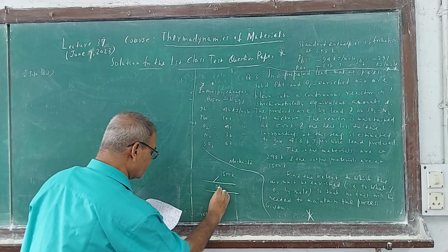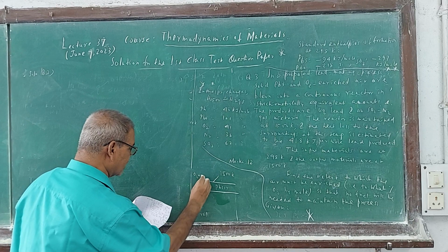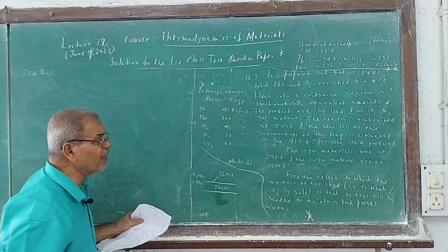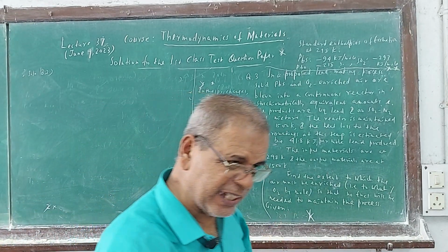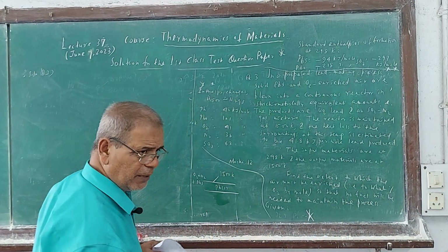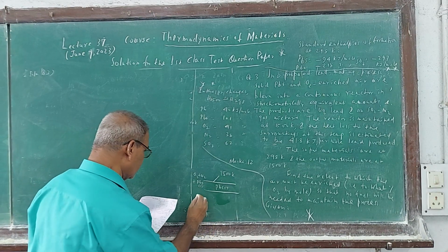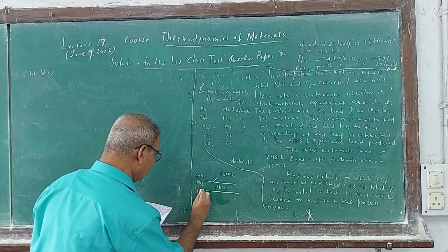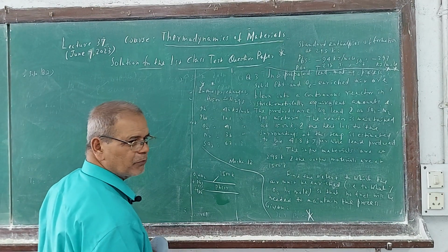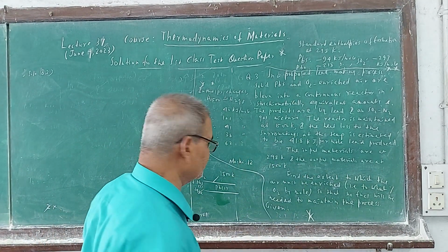Liquid lead is produced. What is entering? Tell me. Oxygen plus nitrogen plus lead sulfide. Why oxygen plus nitrogen? Oxygen enriched air. Generally speaking, oxygen and nitrogen, exactly as I write. Lead sulfide is solid, you may write solid. What temperature is this? These are entering at 298. They are sprayed in, forced into this with the blower, since solid is there. Gas is going and solid particles are going, getting into the furnace.